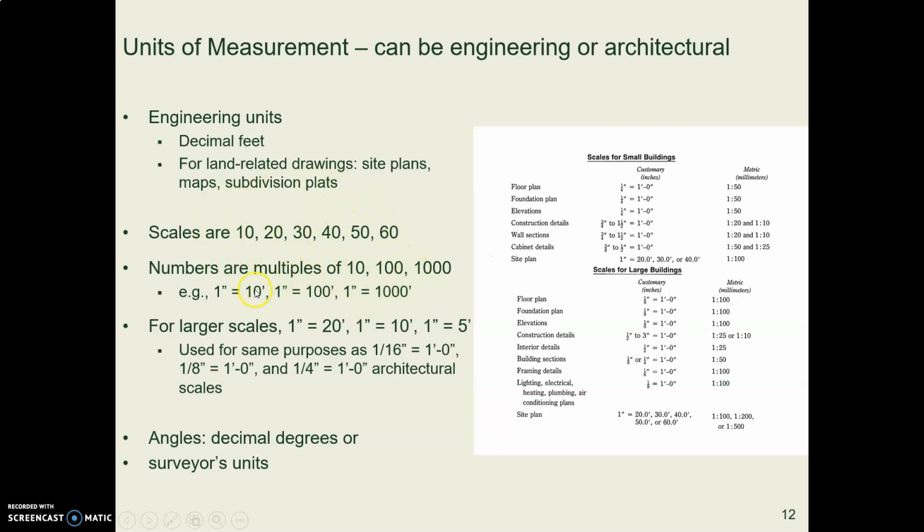So you might have 1 to 100, or 1 inch equals 10 feet, or those kinds of numbers. In some cases, you are using architectural scales. So you might have 1/8 of an inch equals a foot, which is the same thing as 1 to 96. Or you might have 1/4 of an inch to the foot, which is the same thing as 1 to 48, and so forth.